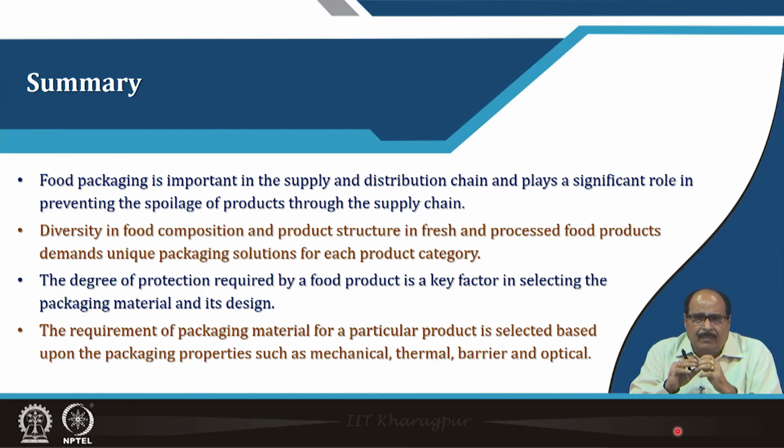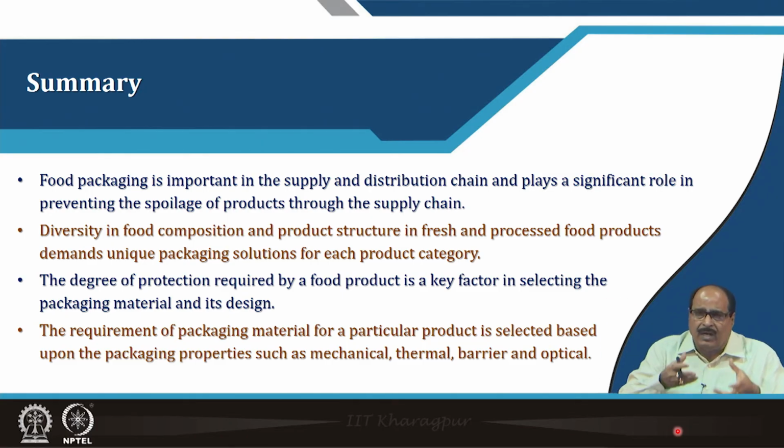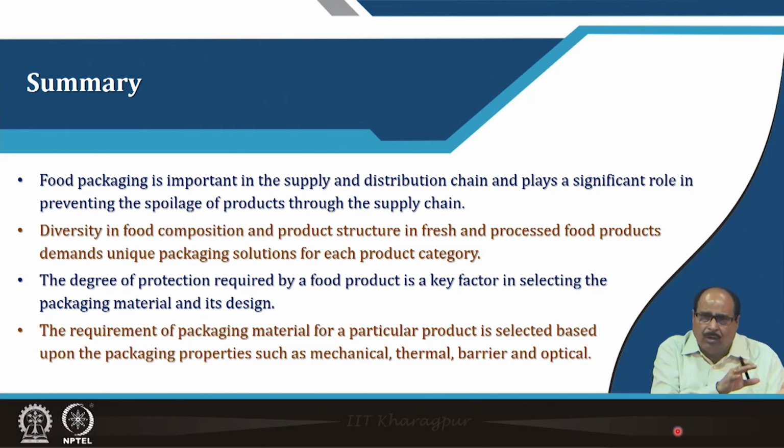But for all these points, the selection of the appropriate packaging material is needed, along with its characteristics and properties: how is the mechanical strength when the packet is being transported, loaded and unloaded; the packet should not tear during transportation; how it will absorb shock; how it will permit or transmit the flow of gases from inside to outside and outside to inside; and light, etc. All these influence the shelf life of the product inside the packet.